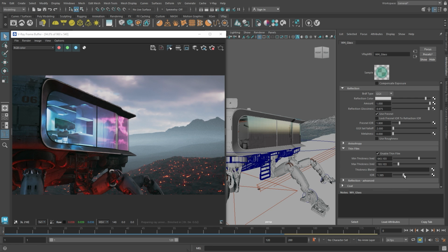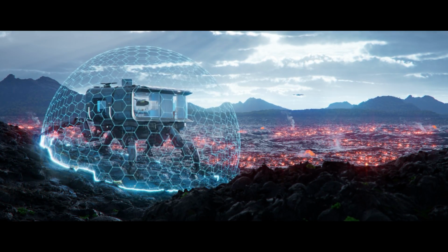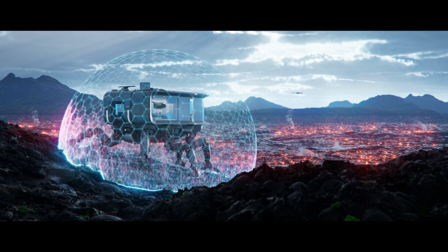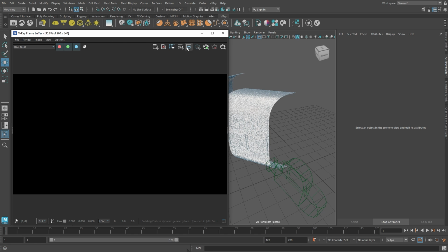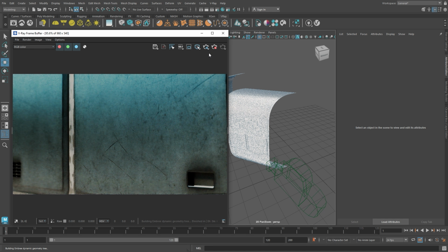Next up was the body of our house. Something we wanted for our house is to be very rough, indicating that it's been functioning for some time. This meant we had to add a lot of little holes for ventilations and some additional detail. One way we can achieve that detail is to add it with Photoshop or any type of texturing software. The problem here is that for each little addition, you have to adjust it in third-party software and export it. In order to not switch constantly between softwares, we used the V-Ray Decal.